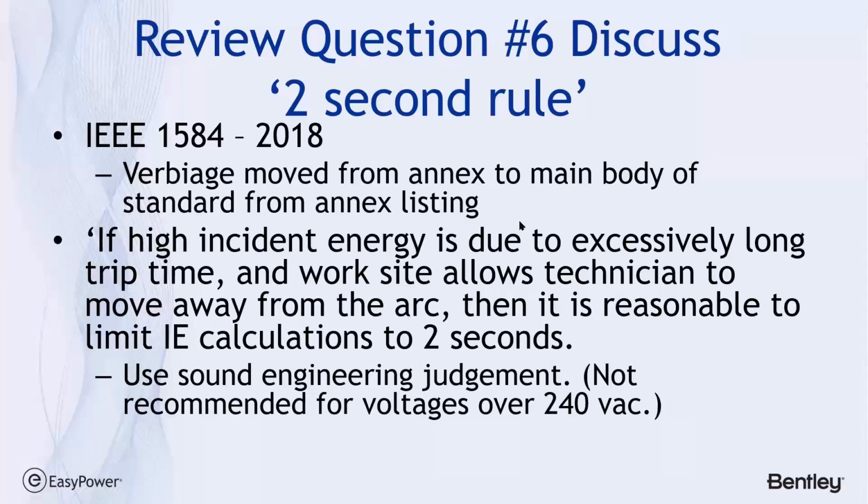Anything below that, it's doubtful that it's going to contribute much in terms of incident energy increase. But certainly as a collective, comparing all motors on to all motors off will give you a sense of how much motor contribution is affecting your results.